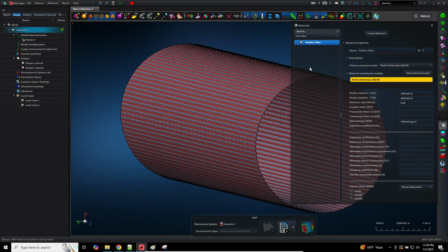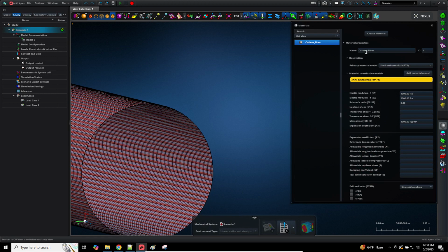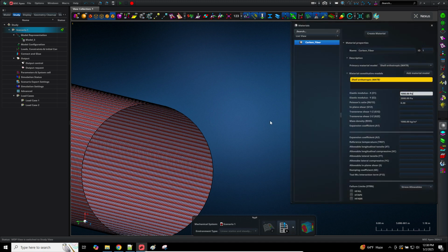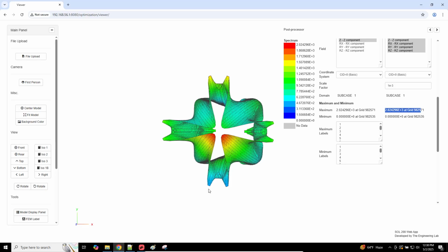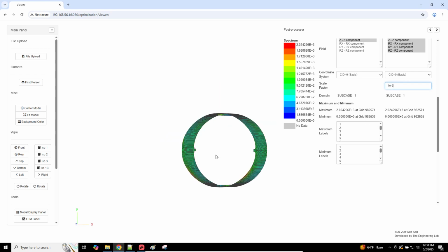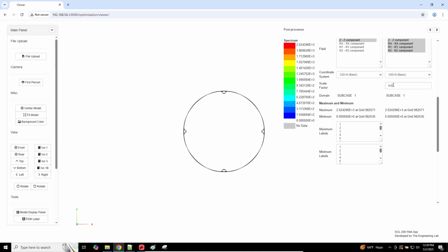If you remember back when I created the orthotropic material for our make-believe carbon fiber, the Young's modulus for the 1 and 2 direction was very small. This is a very soft laminate, if you will. The layers are soft. So when I give this a pressure, the deformations are very, very large. If I were to use more accurate mechanical properties, I wouldn't get such a high deformation. But here, what I'm going to do is scale it. So let's go ahead and scale this a little.